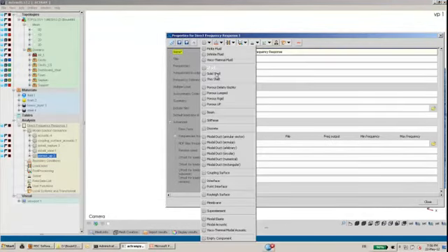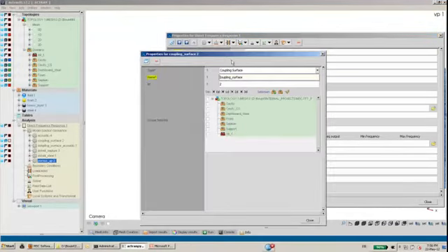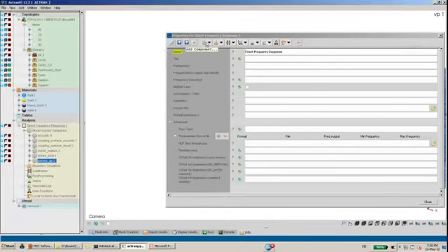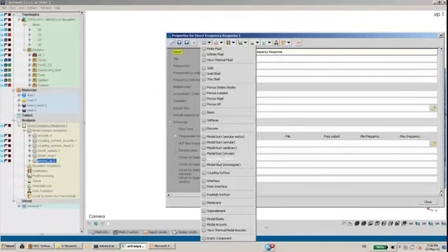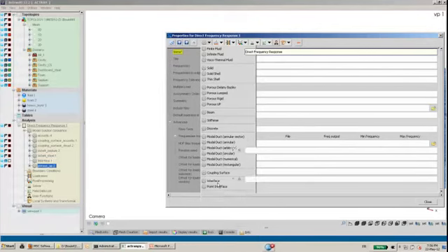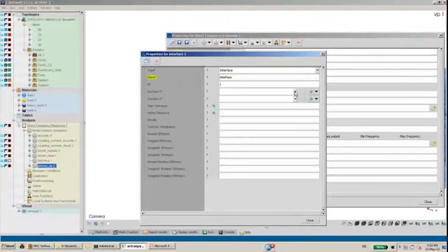And then I also need to create a structure coupling surface, and the structure coupling surface will be the septum, because I want the cavity to be connected to the septum layer. And then to actually make the connections, I need to couple these two coupling surfaces with each other, and that's done through an interface where I will select the two coupling surfaces.